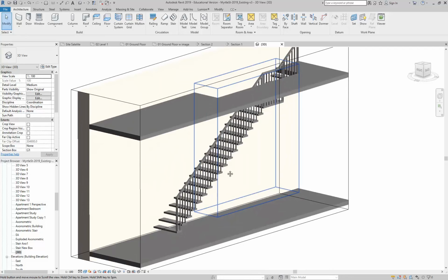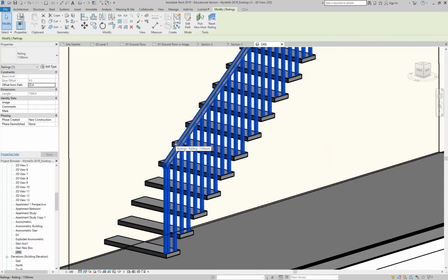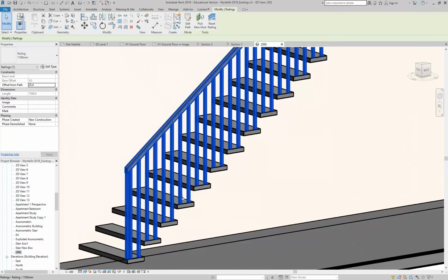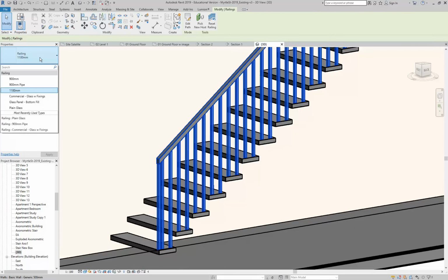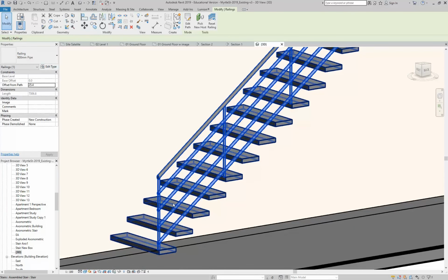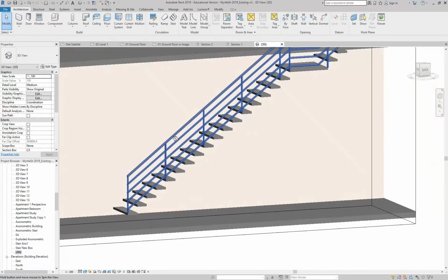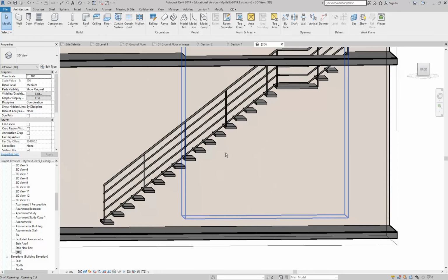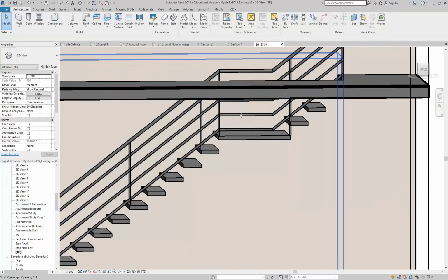And yeah, so we'll go on to balustrades later. Balustrades are a bit more involved, but for now, just make sure you realise that that awful vertical paling balustrade can easily be changed to one of the better options, like the 900mm pipe, which at least gives you horizontal balusters. Do you know what the limitation with those is? Yeah, that's right, exactly. When it's over 4 metres, I think it's 4.5 metres above the level below, you can't have these horizontal ones anymore, because again, kids are mostly, not just kids, but mostly, they can climb up them.